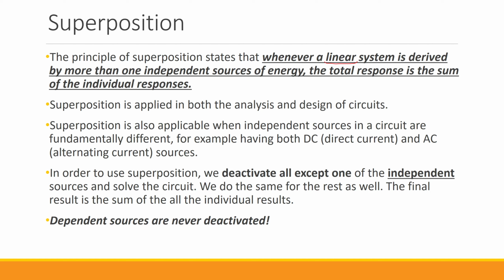The superposition states that if you deactivate all the sources, and then you apply them one by one, or one at a time, and find the individual responses of the system to each individual source, after you solve that circuit 5 times, you can sum all the results, and then you get the result as if all of them were applied at once.